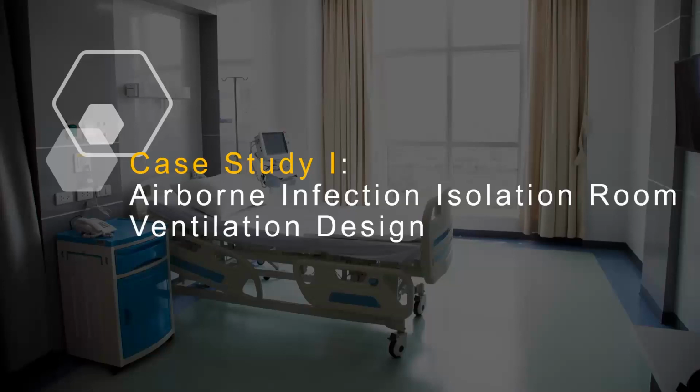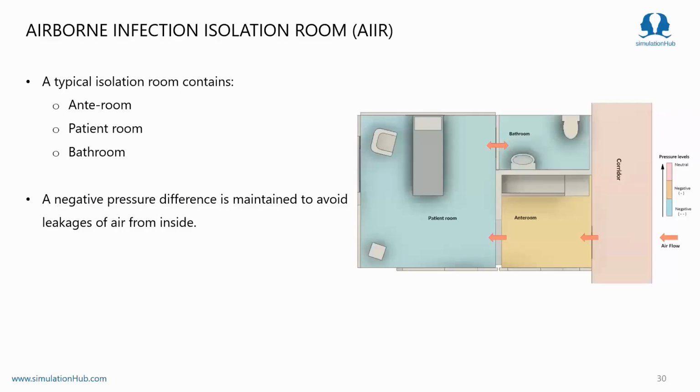So now, before directly going into the CFD problem, let's have a look at the typical construction of an isolation room. Here on the right hand side you can see the isolation room contains an anteroom, a patient room, and is attached to a bathroom. As this isolation room is designed to control airborne infection, it has to maintain negative pressure, which avoids the leakage of air from inside to the outside.